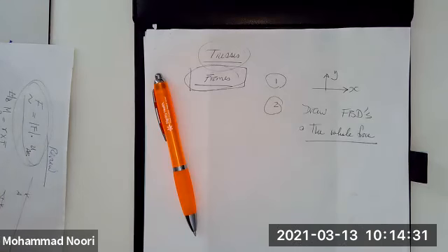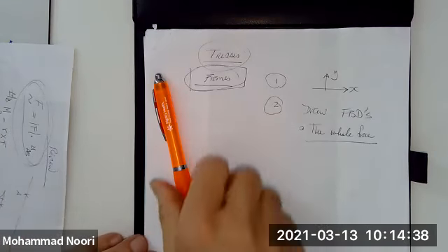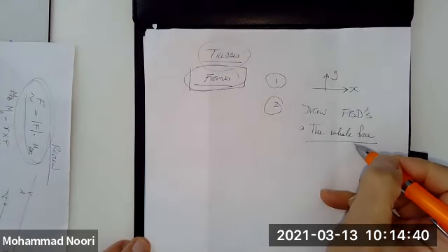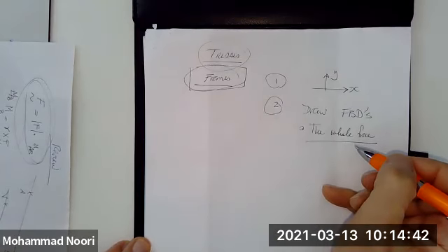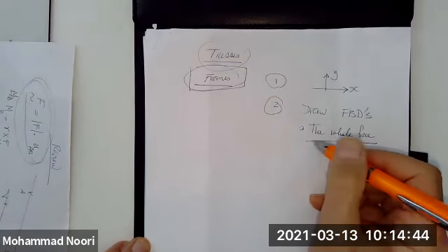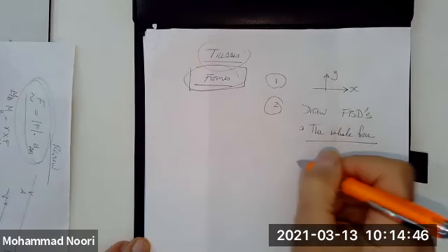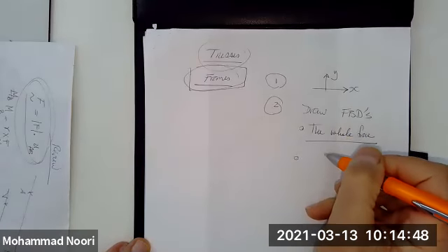Consider the structure as one rigid piece that is only connected to some external supports. So you draw the free body diagram, which consists of only the applied loads and the loads coming from those supports, right? Step after that is what?